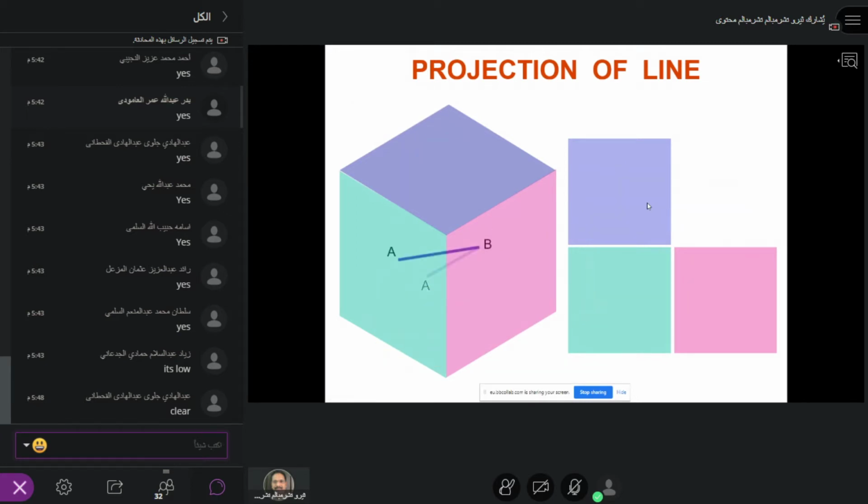Okay, now if it is inclined to the front view like this, AB is in this orientation, and the rotation is about the y-axis. Okay, now what could happen? You could see a distorted top view and a distorted front view. Only the side view gives you the true length.